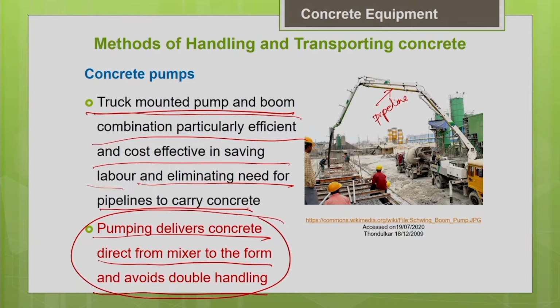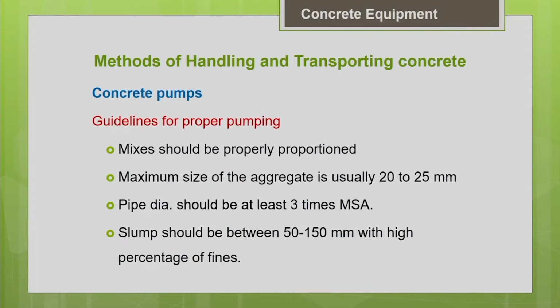Directly you are delivering the concrete from the mixer, the transit mixer or whatever device, directly to the formwork. That way you are avoiding the double handling of the concrete. There are some guidelines for proper, successful pumping that we should always keep in mind. If you decide to go for the pumping method for concrete placement, that decision has to be made even during the mix design itself. While you proportion the concrete mix, you should decide about the concrete placement method.